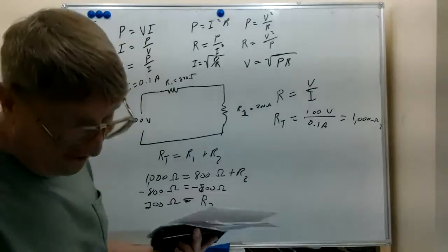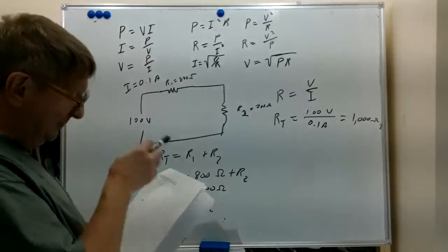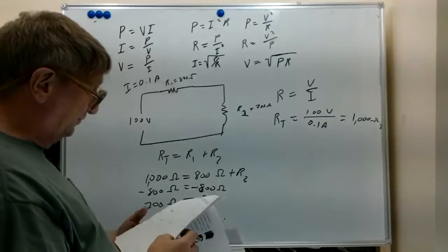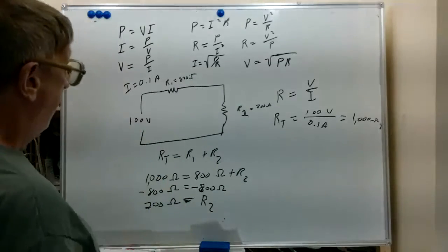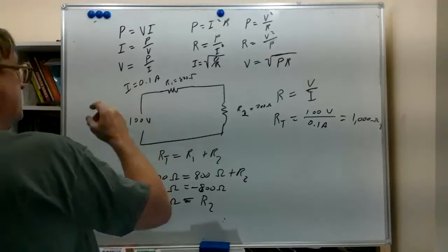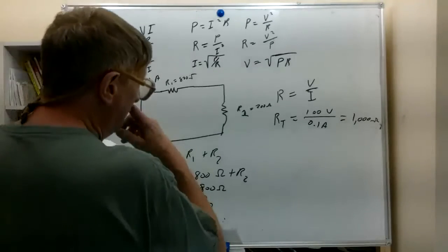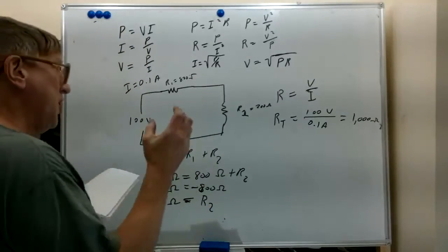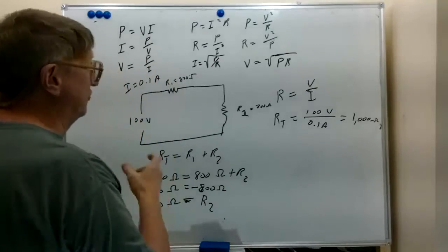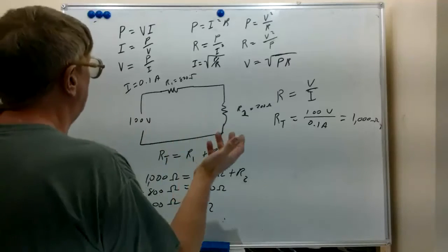So we've successfully chosen our resistor based on criteria that were given. Now we're going to quickly look at, we chose a resistance. We also need to choose a wattage rating. If we put in too small of a wattage rating, which is usually physically smaller, that resistor will fail.